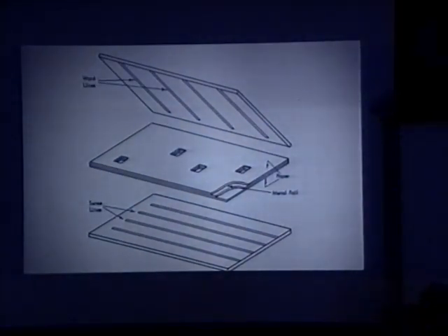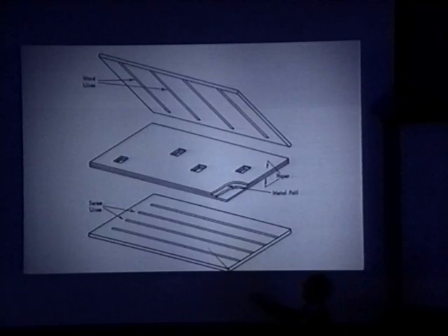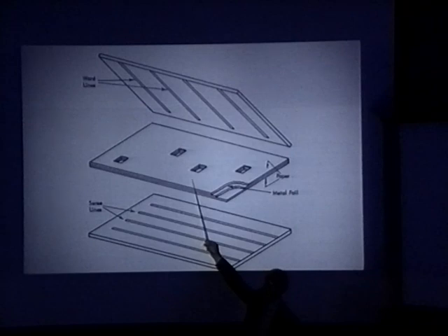Now finally, I'd like to talk about our capacitor store, which was developed in research. And I'll be talking more about this device which came back to haunt us later. Sense lines on one board, word lines on another. A card with a metallized internal plane. You punched holes using a perfectly good card punch where you wanted a 0, and you left the plane intact where there was a 1.